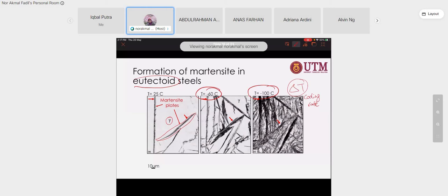For example, the austenite temperature is 750. So to achieve this, delta T is only about 75. But imagine delta T equal to 850 degrees Celsius. So per second, this one is a higher cooling rate and very rapid cooling, and it will produce greater martensite formation.